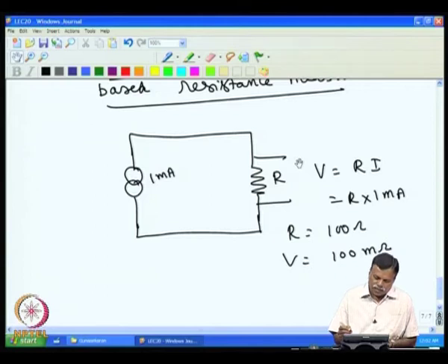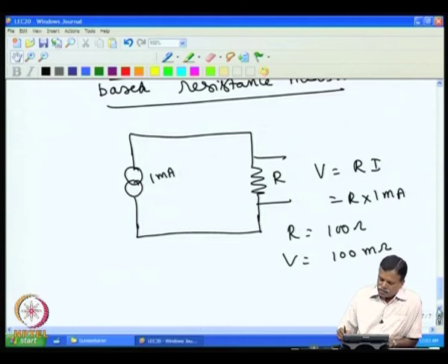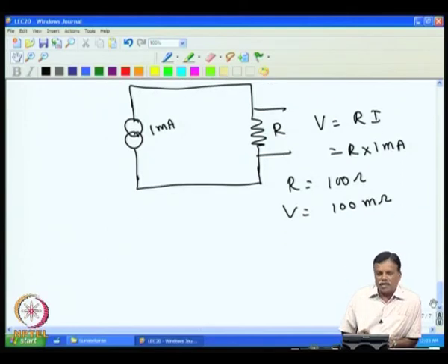Now, we depend upon this current source to get this voltage, but we have to obtain this current source using circuitry, and that current which we fixed at 1 milliampere may not be 1 milliampere at all room temperatures, because the main problem in electronic circuit design is room temperature variation, because it can make the circuit performance deteriorate.